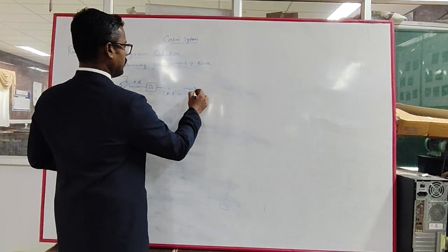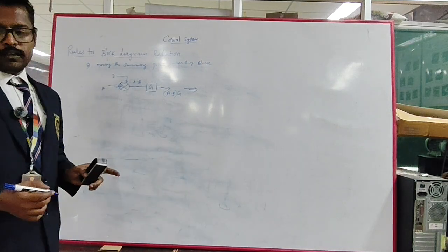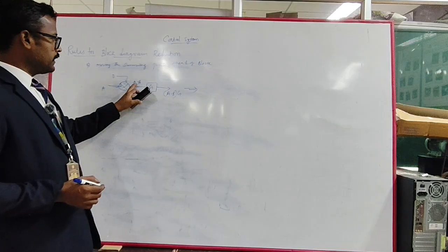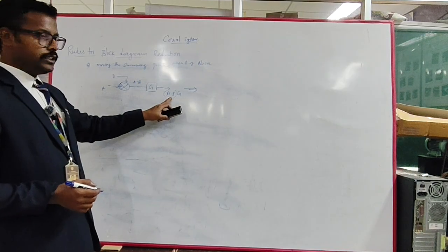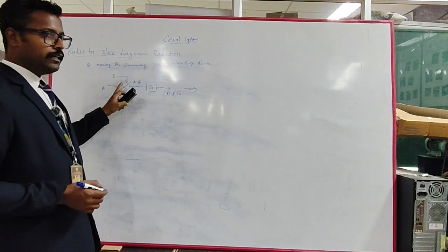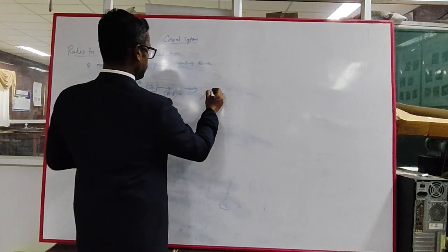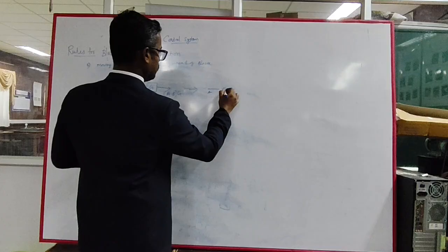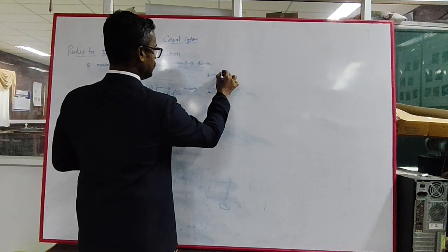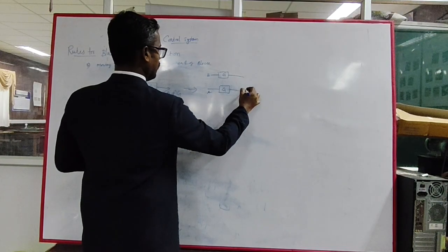So what we will get, if I am adding after the block, is the final outcome A into G minus B into G. So before adding, I have to multiply A with G and B with G. So A is given to G and B will also be given to G, and both the things will get added up.